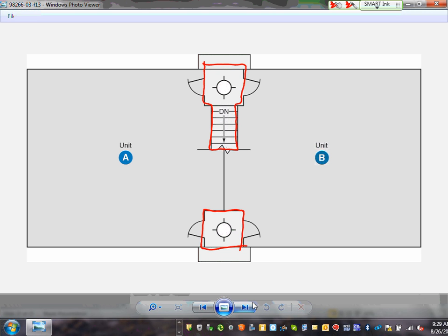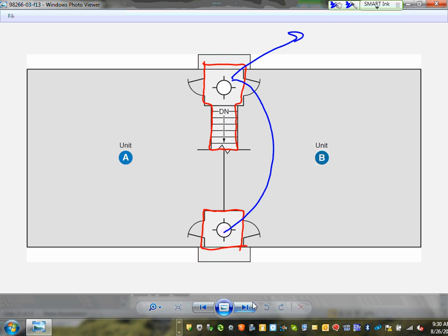So in an apartment, guys, all the common stairways, and if we don't have a lot of common bathrooms in the US, but common stairways, any common outside lights, garages if it's common, all these will be coming from a separate panel. So these two lights here, these two will be going to circuit number 1 from panel number 5, from a separate panel.